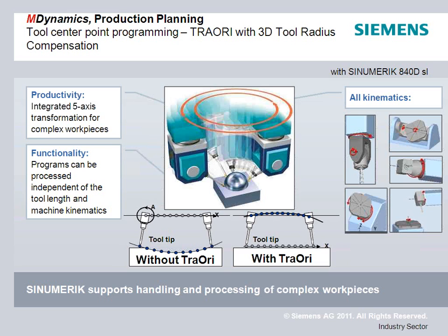But if you can give it some long blocks, well, program what you actually want. If you have a structural aerospace part and you have some long blocks in it, give it the long blocks. If you have parts that have complex curves, feed it short blocks. Either way, with the internal handling of the kinematics by the Priori functions, you're going to end up with the smooth surface on the right.